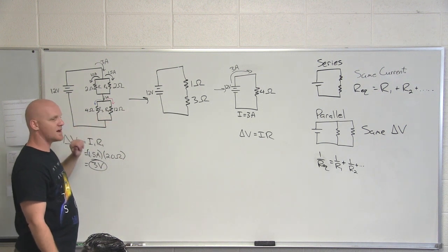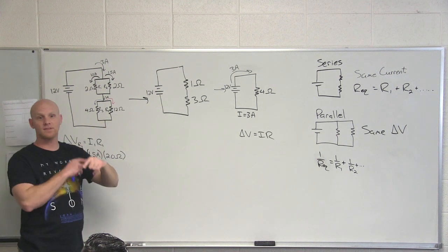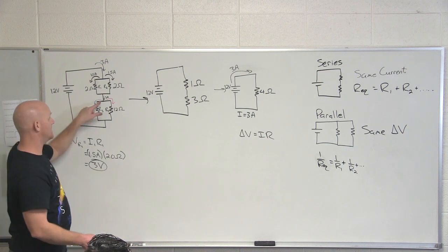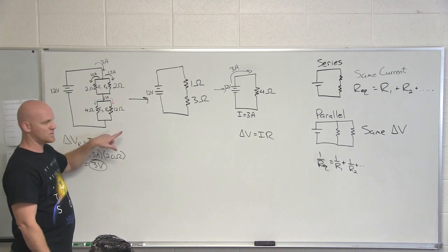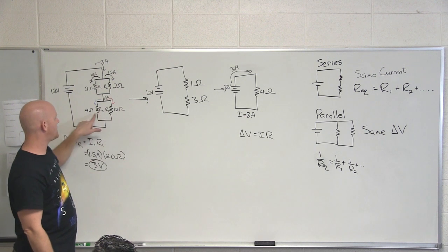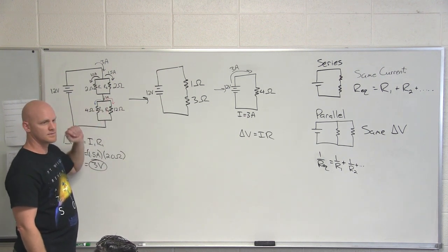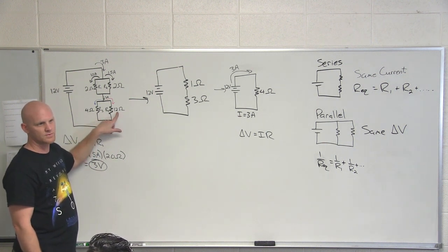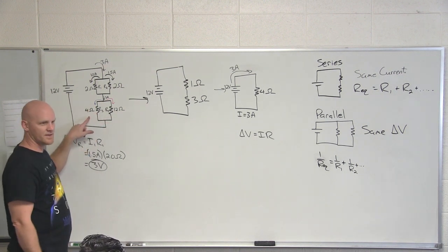But your current is not proportional to resistance, it's inversely proportional. And so now the one with more resistance actually gets less current. Again, we said the currents prefer the path of least resistance, and that's this branch over here. So if you notice, with capacitors, we said the charge would have been bigger on the bigger capacitance side. And in fact, if these were capacitors, what fraction of this total charge would have been on this side? 3/4. Well, guess what's going to be true now? It's only 1/4, and 3/4 will be on the other side.